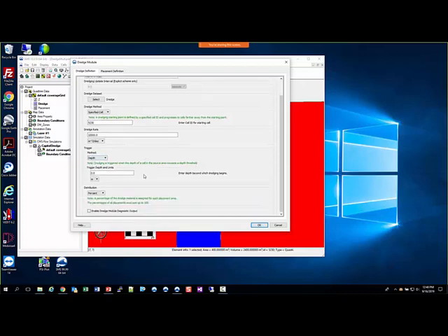And there is a little bit of information here. So when you have this selected as depth, you can see the note, dredging is triggered when the depth of a cell in the source area exceeds a depth threshold. So in this case, we're going to use a value of 6 meters. If we change this to volume, then of course it's a volume of sediment instead of a depth. And then percent, a certain percentage of cells in the source area exceed the threshold depth. So you can have several different ways of selecting this. We're going to do this particular case as depth.